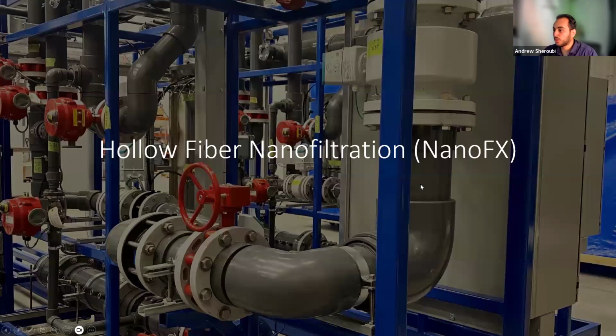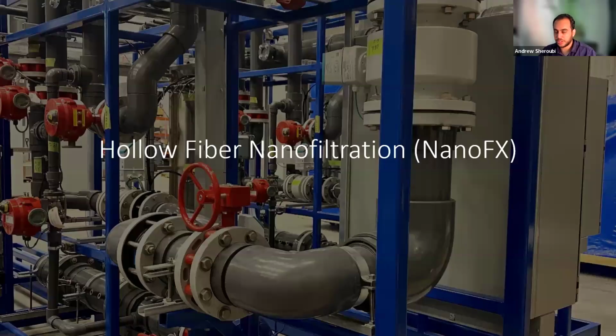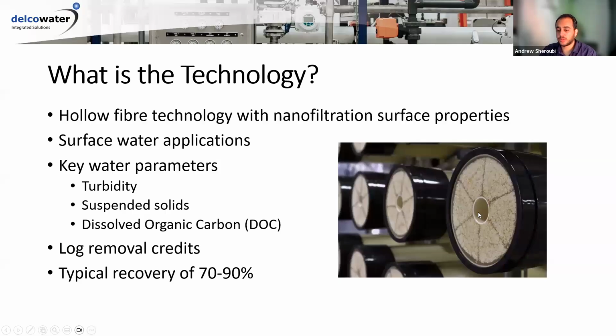The final technology I'm going to go through super quickly because it's a newer technology is called hollow fiber nanofiltration. And if you've been following along with me, these are two different things. What they've been able to do is create basically a UF membrane, so the same spaghetti strands in a vessel, but when they're creating the membrane layer, they create a charge on top of it.